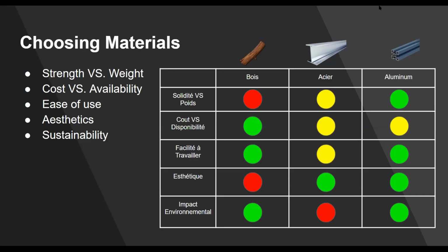I think it works really great. I built most of my frames out of that, a mixture of steel for just the outside parts that I really wanted solid, and then using aluminum for all of my joints and connections, because it's really easy to work with. You can either drill right through it and have a nuts and bolt system, where things that you want to be a little bit more removable are perfect for that. Otherwise, you can use your self-tap screws in those and they hold really, really well. It looks really nice.